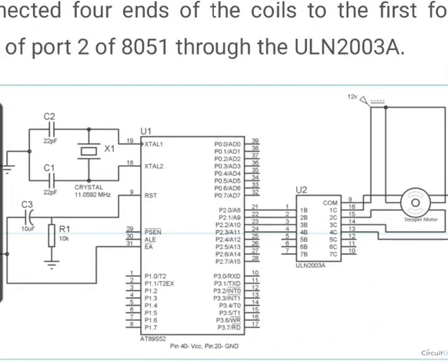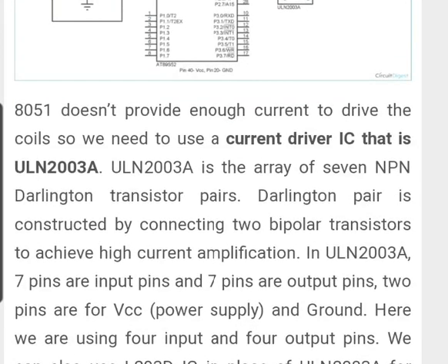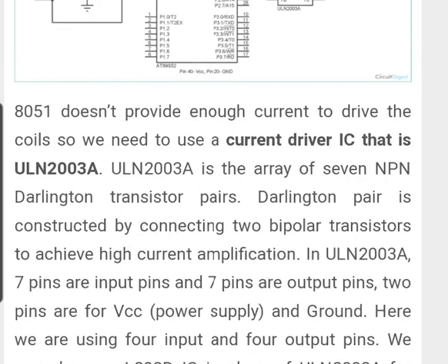Pin number 20 is ground and pin number 40 is VCC. So 8051 is connected to the stepper motor through ULN 2003A. It is a mediator between the stepper motor and the microcontroller. Now 8051 doesn't provide enough current to drive the coil.